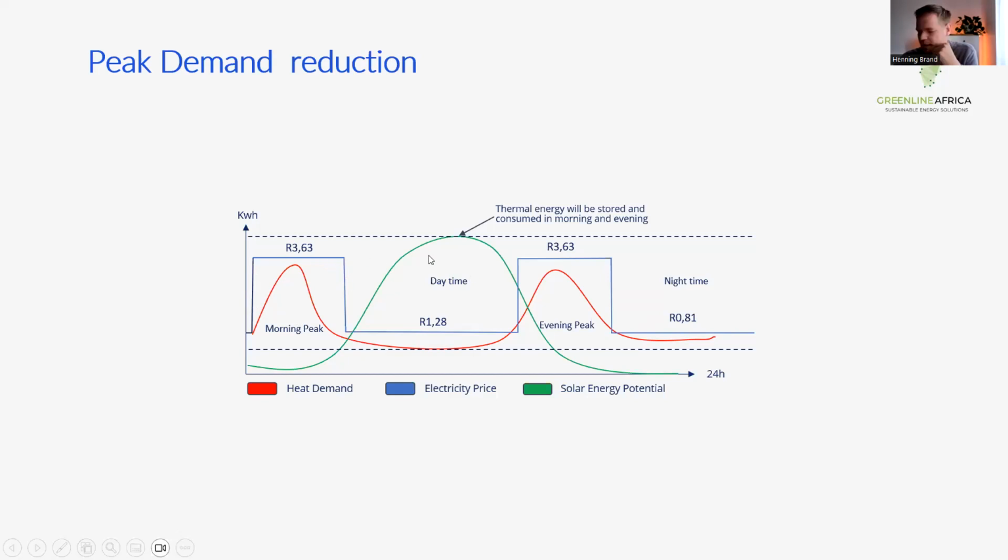So what it does is greatly reduce costs, because during these peak times most countries have a much higher electricity price, when the energy grid is very strained. And if we put in thermal storage, a thermal battery, in combination with renewable heat pumps, solar thermal, such renewables, we can get much better paybacks than if we use only solar thermal, because of this peak demand reduction.